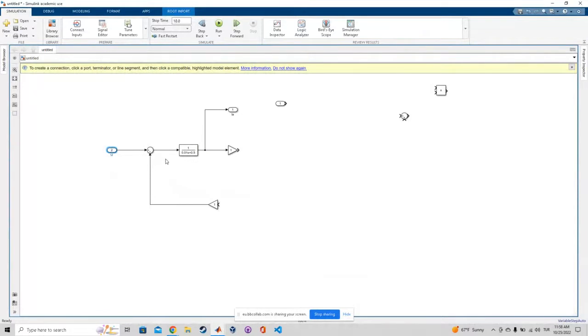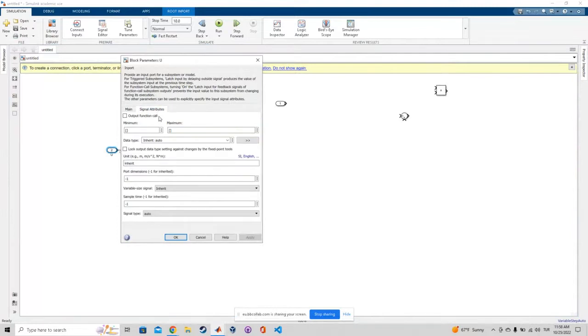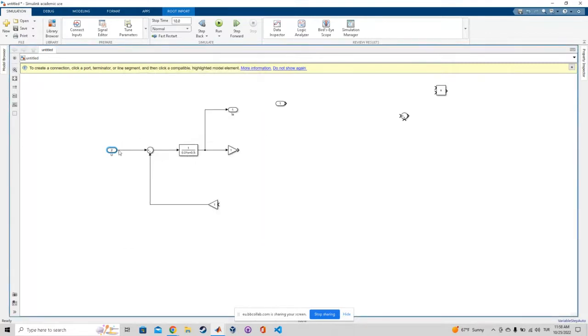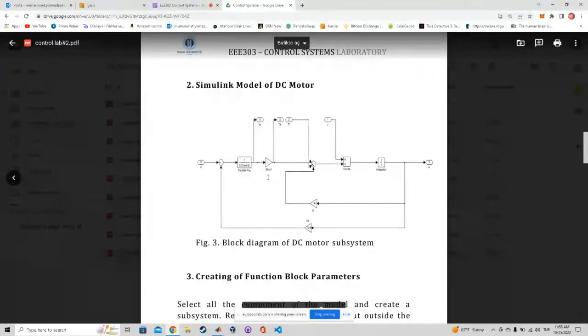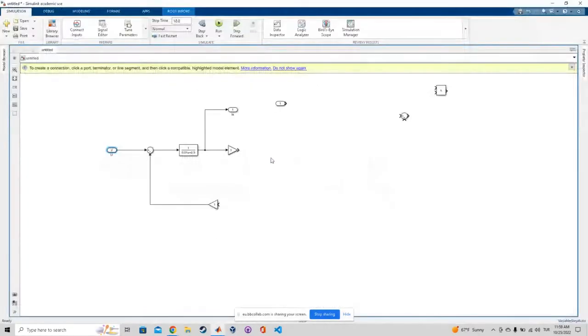And let's change the names also here, don't forget it. Our U input voltage. And then when you double click it here, signal parameters, you can see your input parameters here. So we're gonna define this input later on, and we give a value to it, like 100 volt. We're gonna use 100 volt in this experiment.